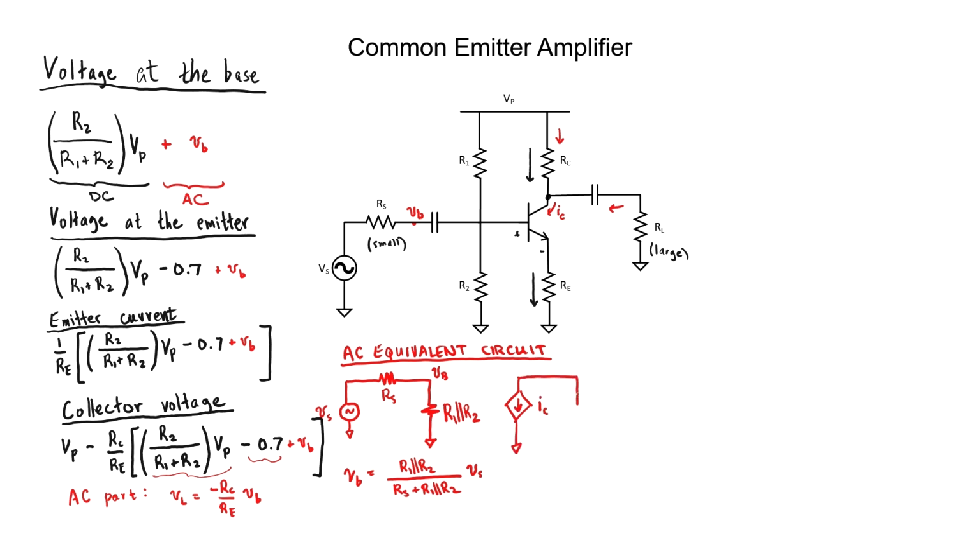The current source pulls current through the collector resistor R sub C, which is connected to an AC ground, and it also pulls AC current through our load resistor R sub L. We have a current divider here at the output. Let me go ahead and label our load voltage and call it V sub L. I could label it up here in our real circuit as well.